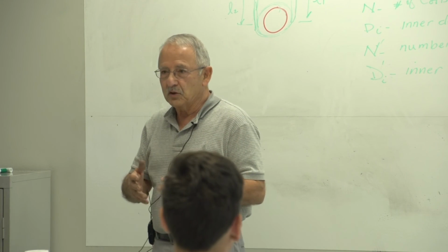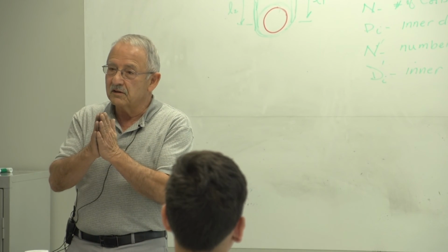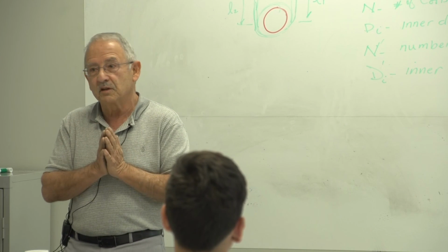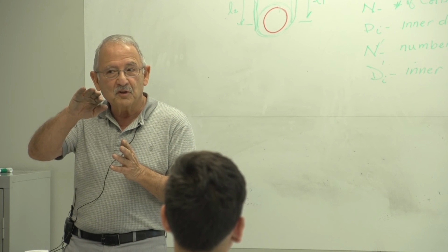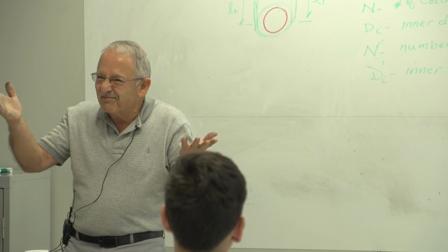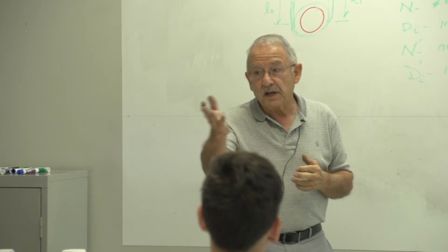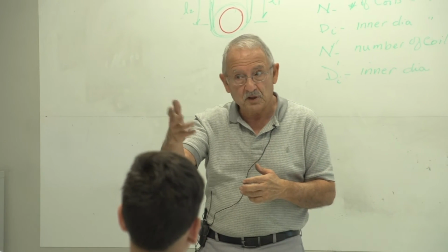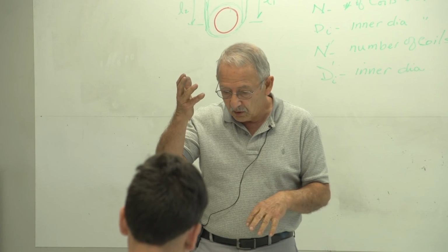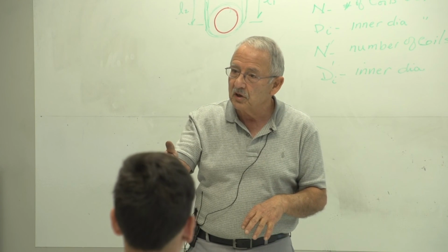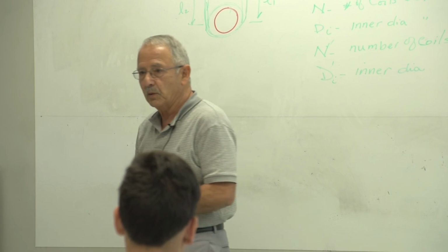And remember that as you get to a higher strength material and yield and tensile strength get closer, it's because the material is becoming more brittle. And therefore, from the time it yields to the time it breaks, not that much. So that's where it comes from. It's an estimate, of course. It's not an exact value. Again, if you are working with a specific material, you should use properties of that material rather than an estimate.